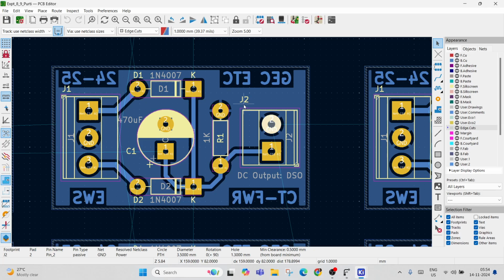So we need to have good design capabilities or a good thought process to make sure that we put enough solder, so that there is no gap between the pin terminal and the soldering pad. So we just need to handle it. We will see that during the hardware session. So that is the biggest problem.